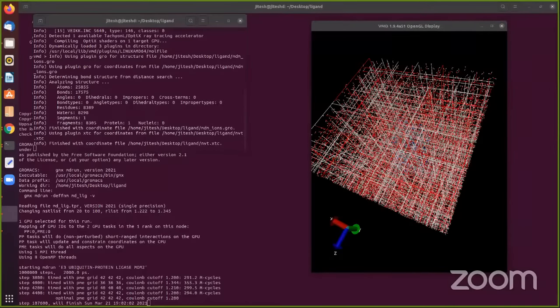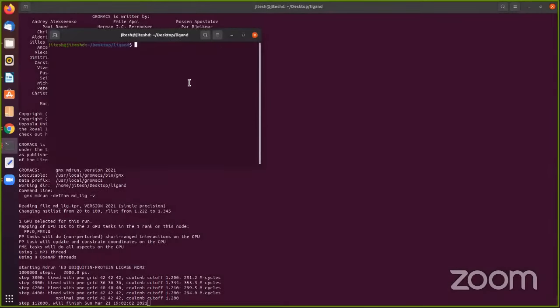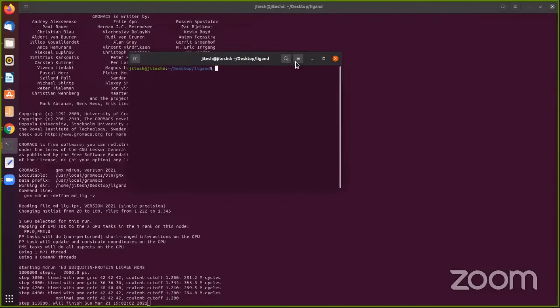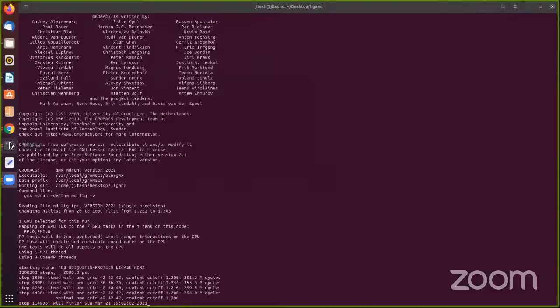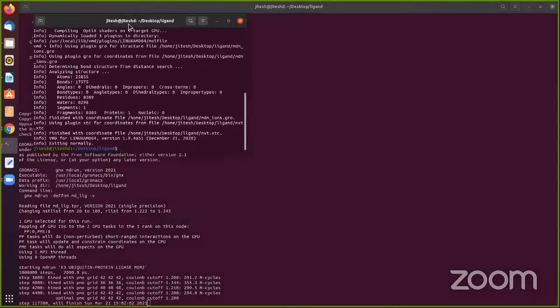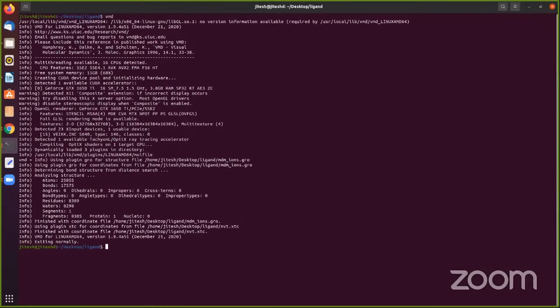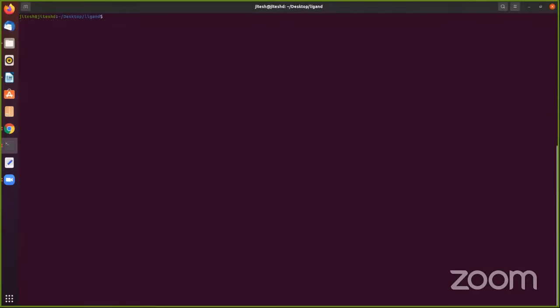So for that, in Gromacs, now our analysis is going to start. For this, Gromacs has provided an inbuilt command called the trajectory converter, or TRJCONV, that can be used to convert the trajectories. I'll show you how to convert these trajectories so that our periodic boundaries can be corrected, and then you will be able to visualize these trajectories in a much better fashion.